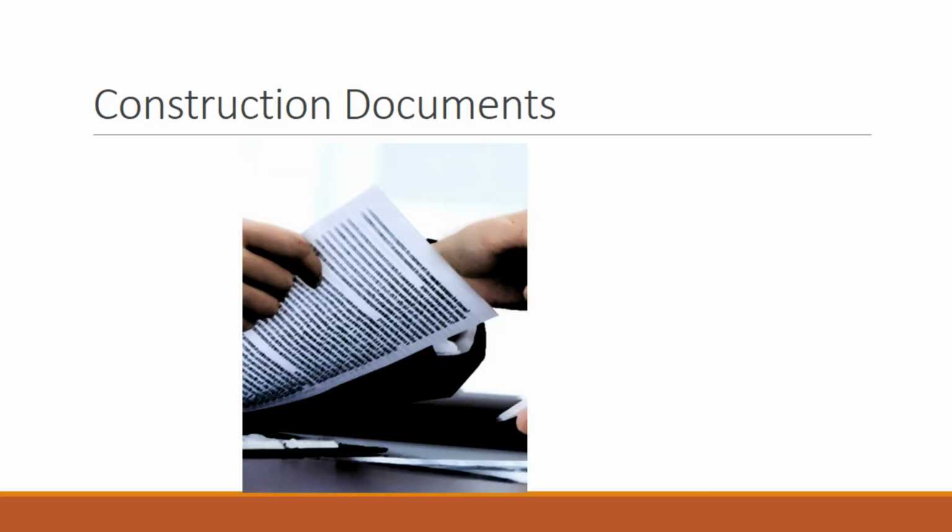And then we move on to the last substage of stage 2, which is construction documents. Now, drawings are completed in this substage to enable the acquisition of permits and the receipt of bids. And the drawings are expanded upon, double-checked, and comprehensive specifications are prepared. A control estimate might be carried out for bigger projects to make sure that there hasn't been any scope creep and to improve the original estimates.